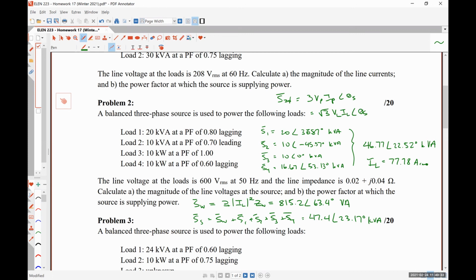So that means there should have been a factor of square root of 3 taken into account here, and then that same factor of square root of 3 taken into account in our last step. Best guess is they were going to cancel each other out, but we technically did forget to do that. So that is going to influence the complex power absorbed by our wire, though, because we were using a current that was square root of 3 times too small. But anyway, a little dumb mistake made in there because I forgot about that factor of square root of 3, but the process is fairly straightforward. So I apologize for making that dumb mistake, but we caught it.